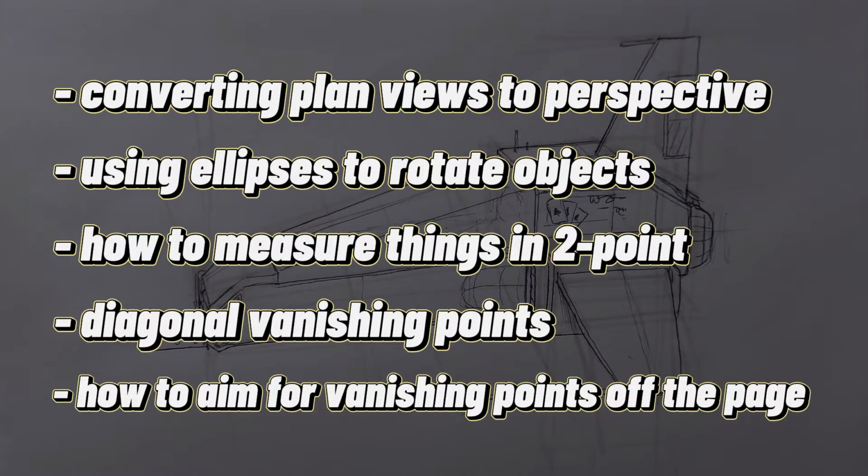In this video, we'll discuss the following points and learn the trickier aspects of two-point perspective. We'll see how we can accurately plot scenes in two-point using a variety of tricks and revisit some of the concepts we first met while learning about one-point perspective.